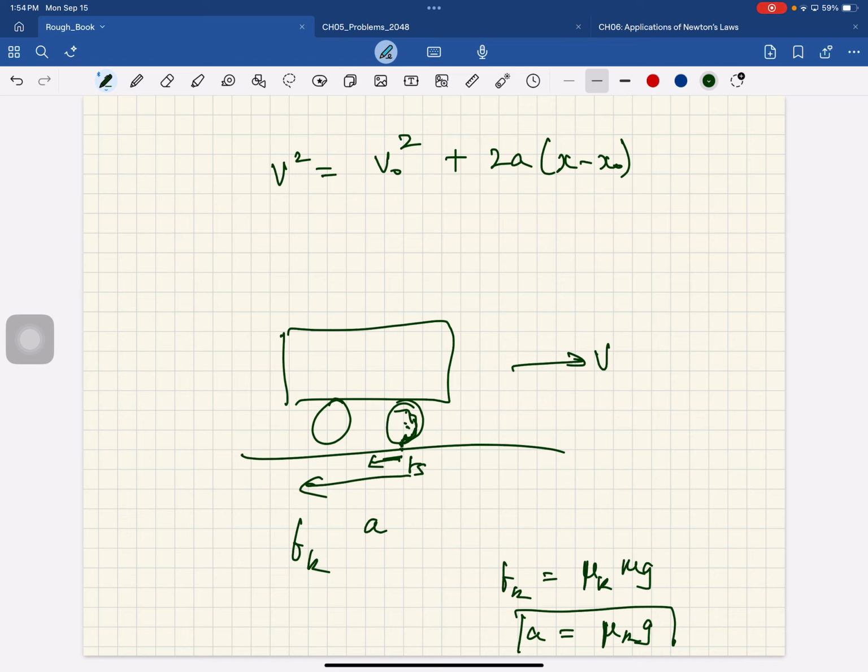So what the anti-locking braking system does is it's pumping the brake for you, about 15 to 20 times a second. It's locking the brake, unlocking, locking the brake, and unlocking. So the wheels keep rolling, okay? And since it's slowing down, the static friction force is acting in this direction. And the maximum static friction force, so the acceleration is mu s times g. You have a larger acceleration, your stopping distance is smaller.